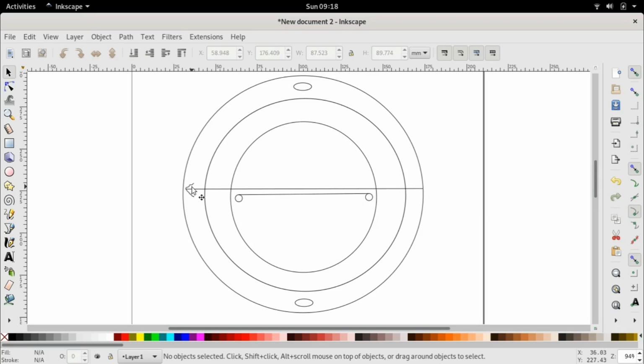This stator flux is now not linking with the rotor. There is almost zero linkage of the stator flux with the rotor. It's not passing through the rotor, right? It is just not passing because that's how the coil is. In reality, of course, this doesn't happen because the rotor windings are distributed, rotor bars are distributed around the circumference. But for now, for our purpose of understanding, we can see that the stator flux is now not linking the rotor at all. There is zero linkage.